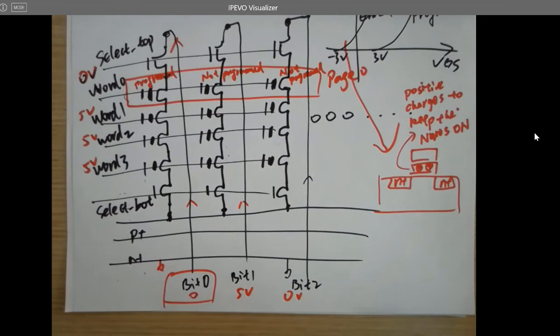The problem is whenever your circuit is being scaled up, and you cannot do LVS, you just don't want to spend the money to fabricate it, right? You have thousands or millions of wires, and any wire can screw up everything, and you're spending hundreds of thousands of dollars to fabricate the chips and cannot do LVS. You don't want to fabricate it.